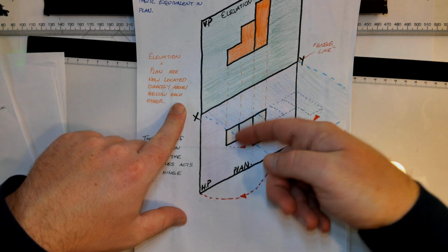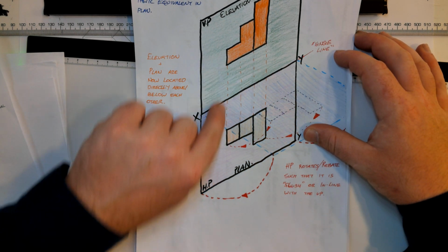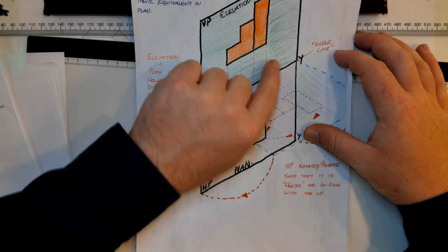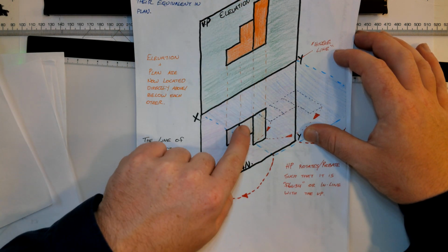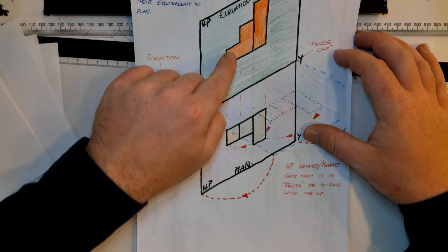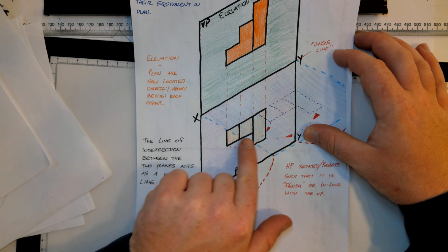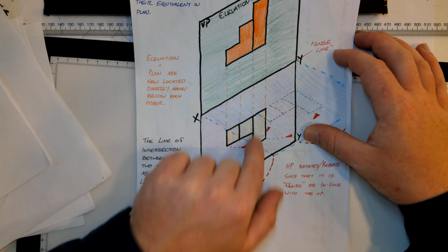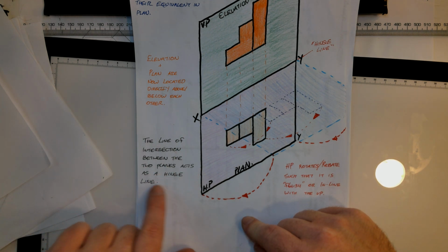If you look at these projection lines here, the dashed lines, you can see that they're directly in line with each other. For example, that rectangle face will be on top, this square face will be here, and this square face will be here. And then if we looked at this L shape, that will be looking in here at this edge, and they're projected straight up.